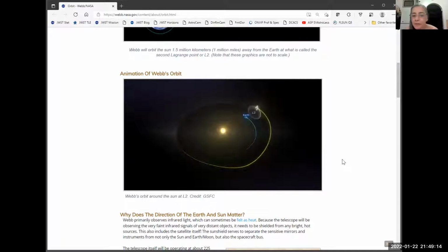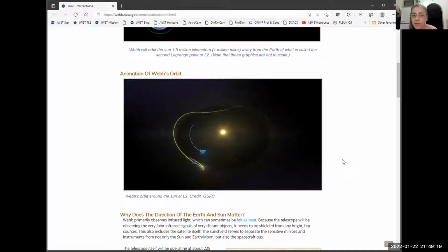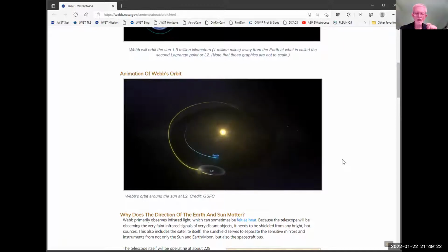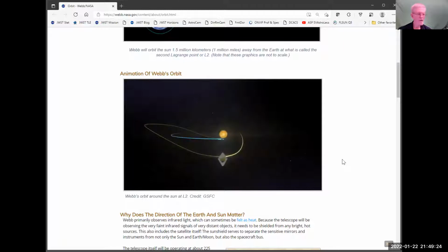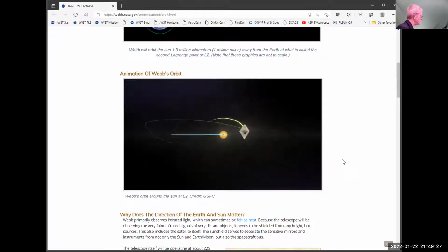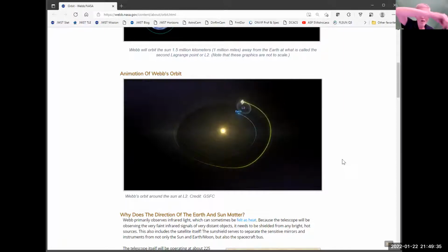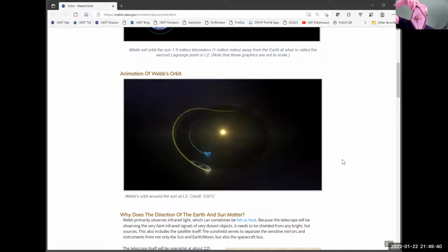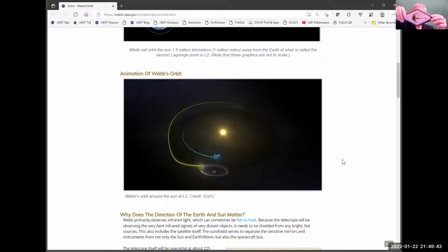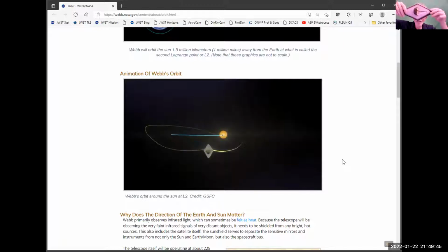No, my question is, when it turns like south, north, north, south, does it use just the momentum, or just the stabilization? No, that's just a momentum wheel. The problem is that the momentum wheels have a maximum speed. So if the telescope is arcing up this way, they're already using the momentum wheels to gain a certain curvature of the orbit. And then if you wanted to turn the telescope like this, you may not have enough momentum left to get up to the maximum spin rate of the momentum wheels.